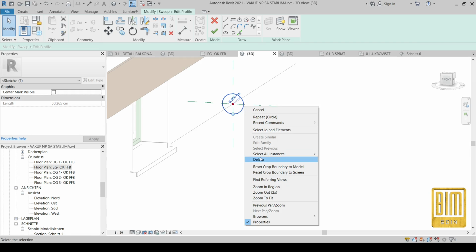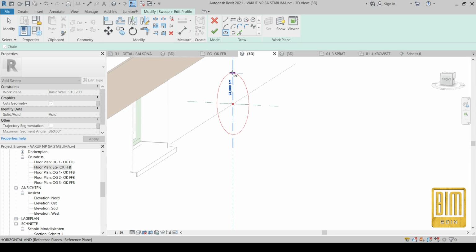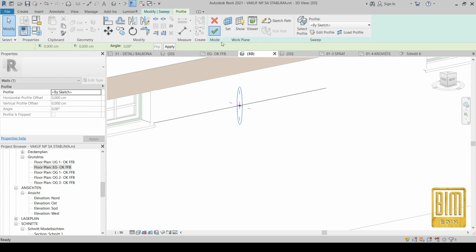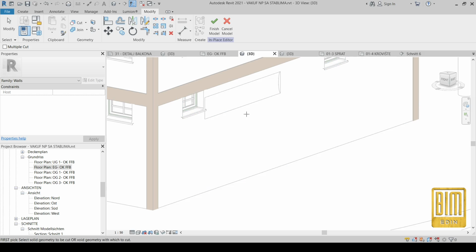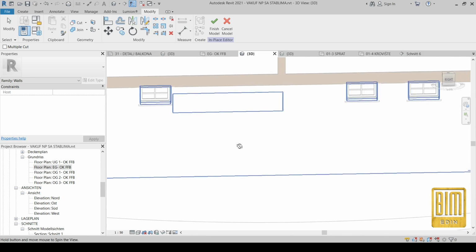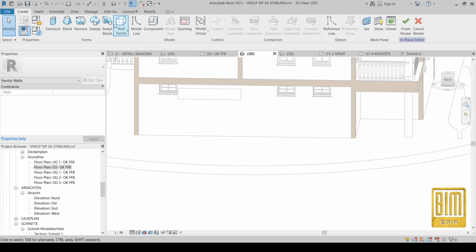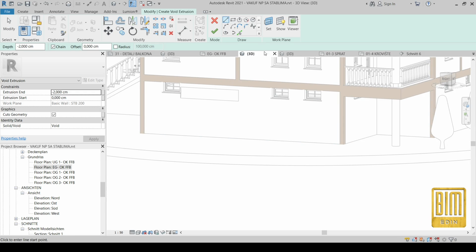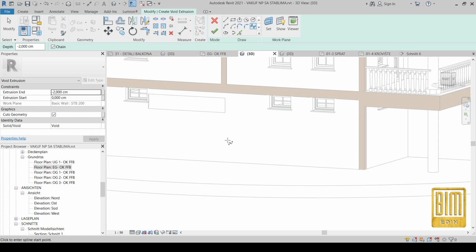All right, I use sweep here. Now I will use this elliptical form to create an opening in or cutting part of the wall. You can see you can create any shape you want. The method is the same. I will just show you how to create an opening. We will pick the reference face, and from here I will create one totally organic opening.